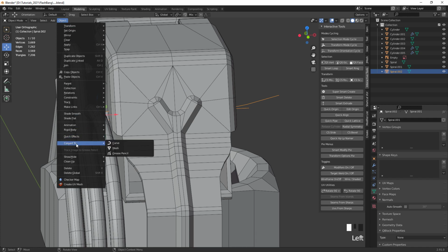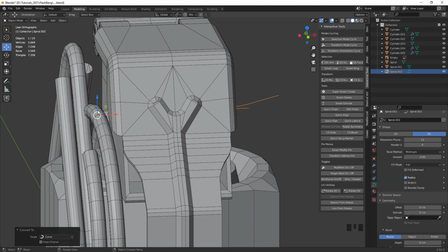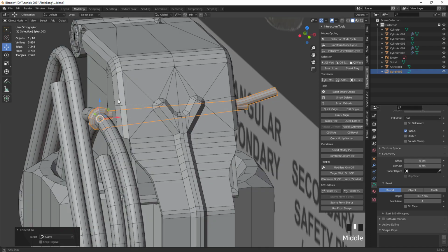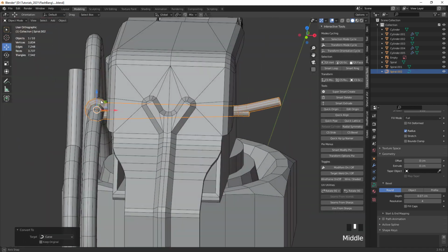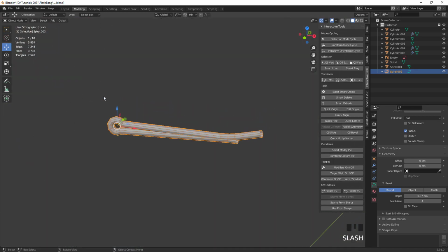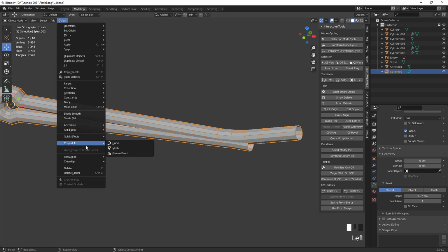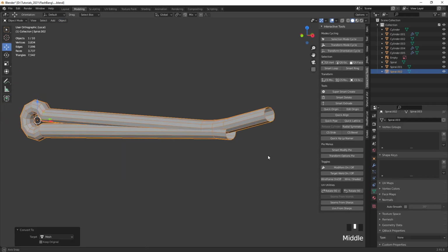and essentially that's this pin. We just want to convert it to being a curve so that we once again can add our depth to it. So I'm gonna have, in that case, a pretty low amount here so that it's not too big. Let's take that into isolation mode. And now I want to convert it to a mesh.